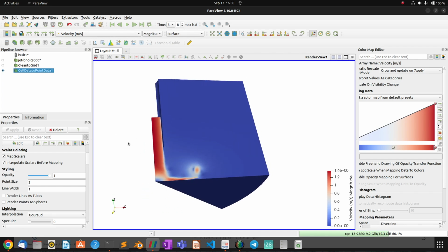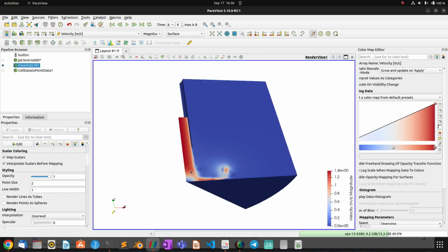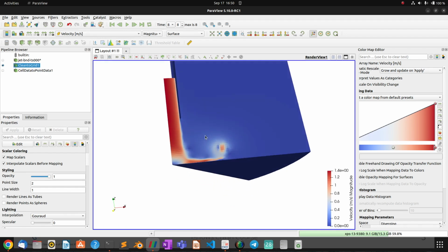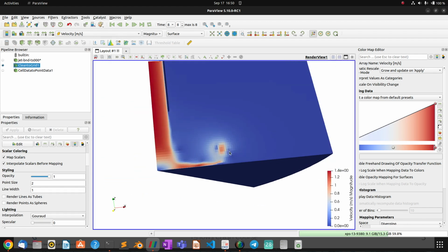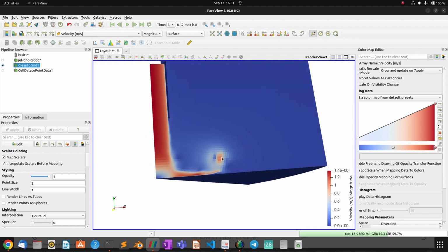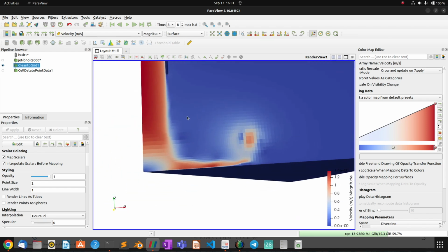You can see it's very smooth. If we don't use this filter as we showed before, it's a bit pixelized, and that's actually the more accurate representation of the flow, because it's not interpolated. But you want to use the filter maybe for some visuals or some technical report. But if you want to look into some deeper details between cells, or you're debugging something, maybe it's a good idea to look at these uninterpolated values of the grid.